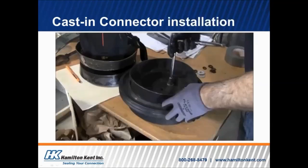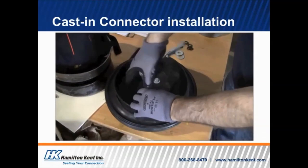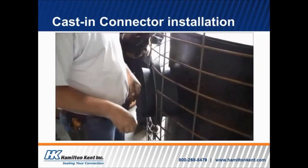Here's a short video that we shot at one of our customers' locations, and you can see initially that he's tightening this mandrel. So I'll show that here in just a second. Here's a mandrel right here that has a connector installed in it, but over to the left-hand side you can see that there's a mandrel that doesn't have a connector in it. So you can see the two pieces that come together in order to basically squeeze against that rubber. So let me get this video started here, and you can see that he's tightening it down so that the mandrel is going to be nice and tight. And then once it's tight and it's ready to go, then you just get it, put it on the form, and he's going to swivel into place, and it's going to fit nicely up against the core of that formwork.